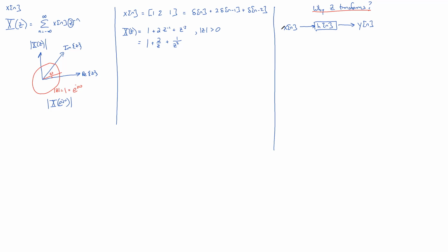And so now we're shackled with the realities of having to live in a discrete world and having to deal with weird things like aliasing and a DTFT that's repetitive, whose highest frequency is only pi instead of in the continuous world where it's infinite. So that's unfortunate. But the fortunate thing is that by allowing ourselves to go in the discrete world, we can compute our output using a convolution.